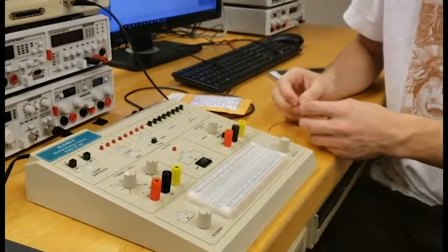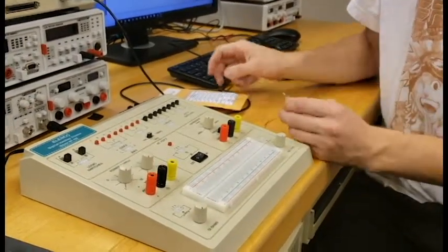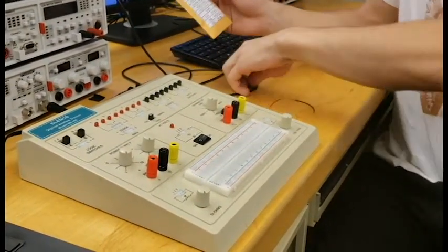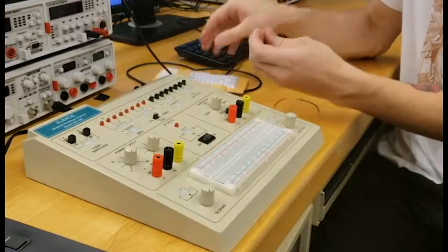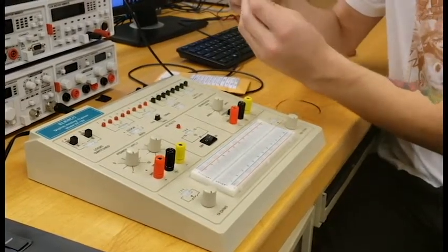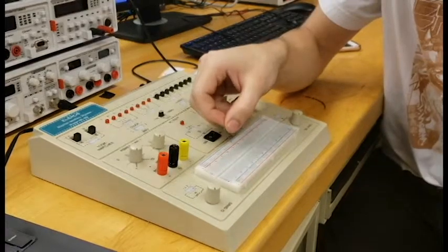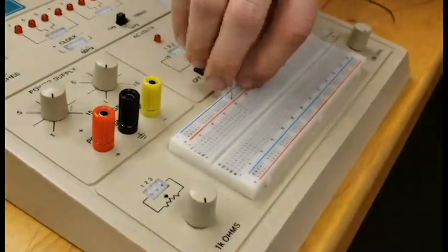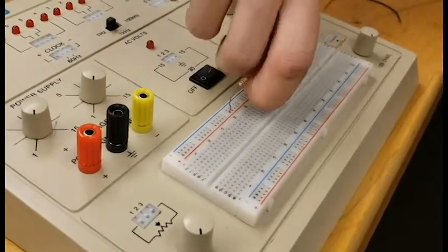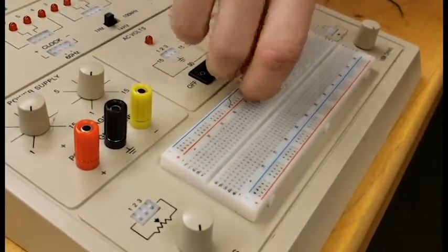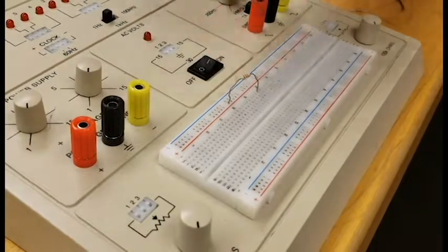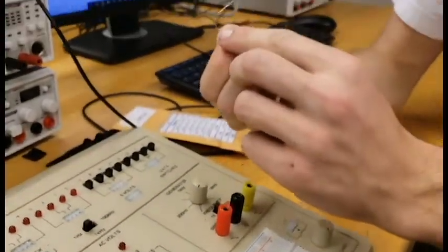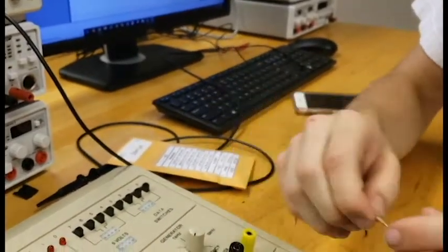So we're going to build a small 2 resistor circuit, and our first resistor is a 1.5 kilo ohm resistor, and the color code for that is brown, green, red. So we check this one, brown, green, red. That's correct. So we're going to put it positive terminal, connect it to column 29, not 30 because that one's blocked. And then our second resistor is a 2 kilo ohm resistor, which is red, black, red as the bands.